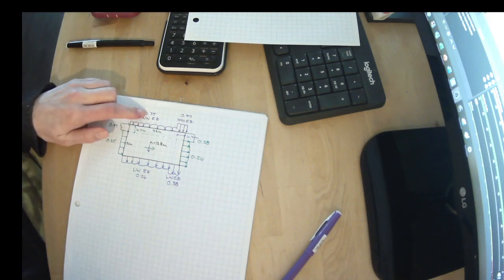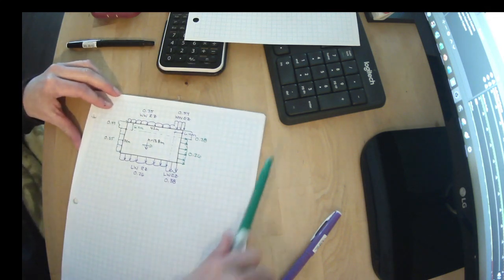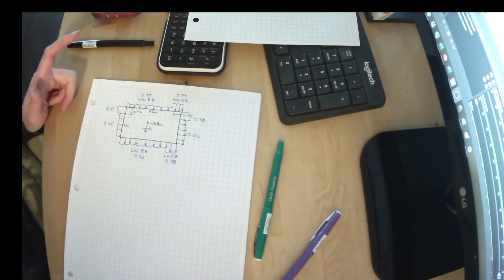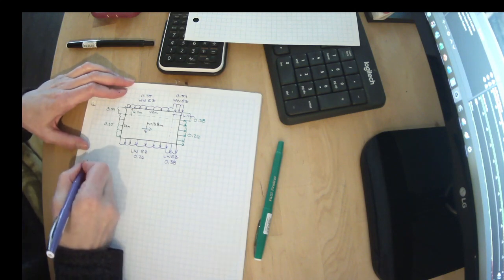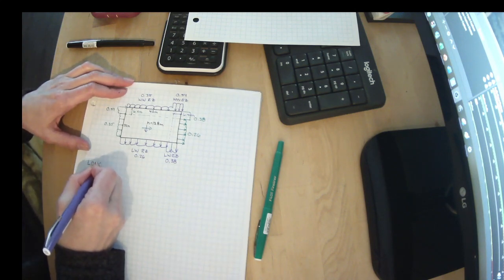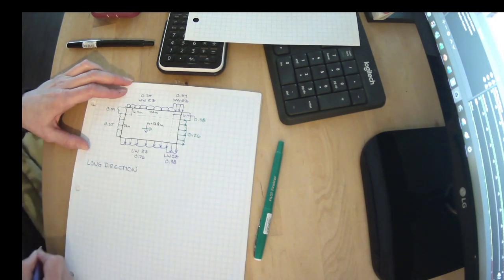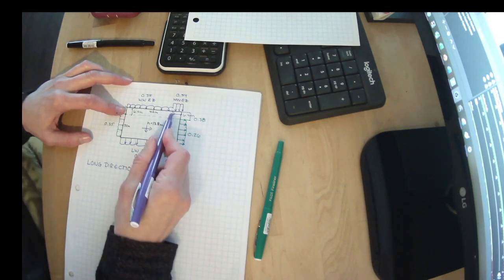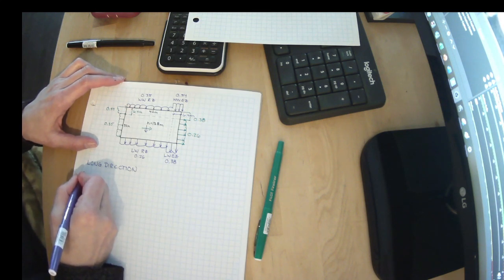We've already built our importance factor, our 1 in 50 year reference pressure, and our CE and our CPCG into all of these. Now it's just about figuring out the total areas of these. So let's add those up. So let's look at the long direction. We have our windward regular zone, so we want our total wind load here.